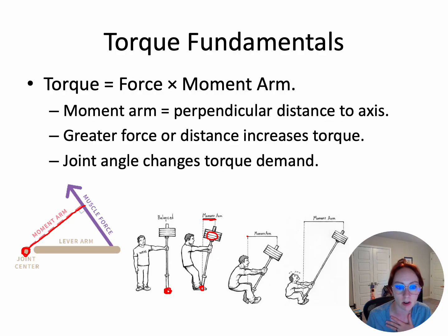And then that moment arm changes even more when you're having to hold it at an even greater angle downward. And then here is another extreme version where you have that joint axis even further down, but also now it's increased in distance. You're having to hold a longer pole with the weight at the end. That moment arm is increased, and so now the torque is going to be increased. That torque demand has been increased.